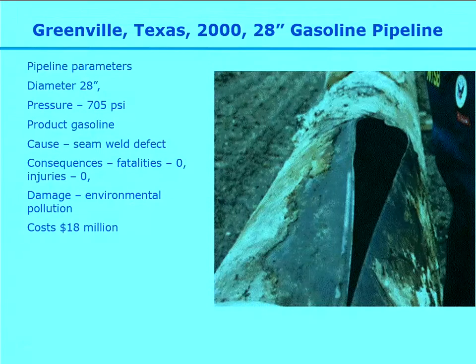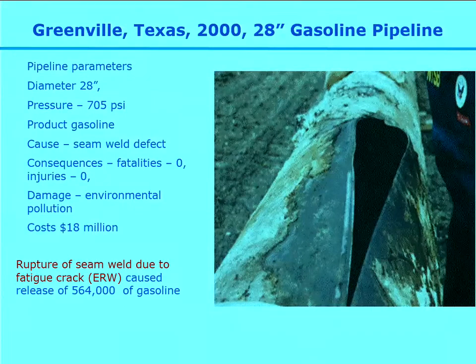So again, it was very prone to failure. Any pipe which was subject to any kind of pressure cycling was a potential failure, and most old ERW pipe has been quite significantly derated to prevent that sort of failure.